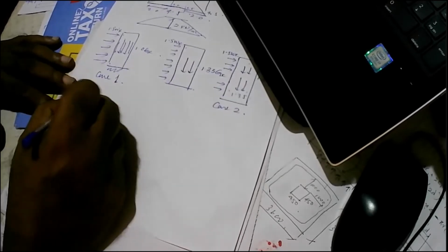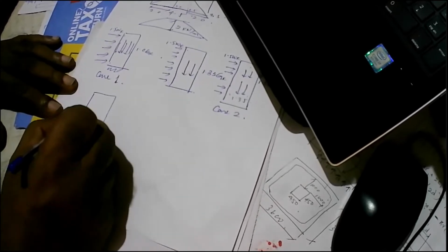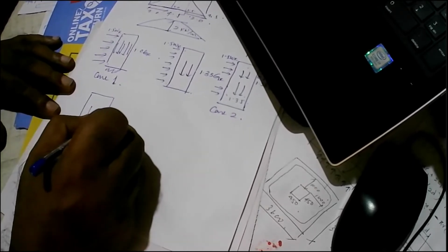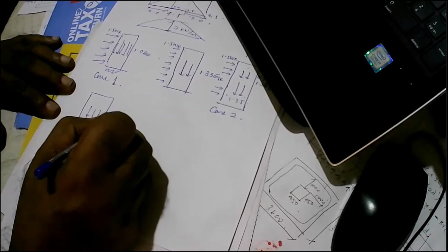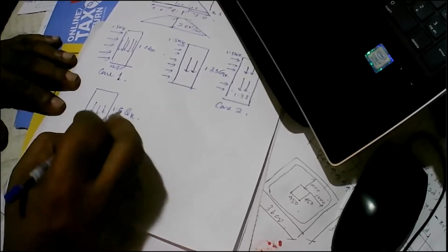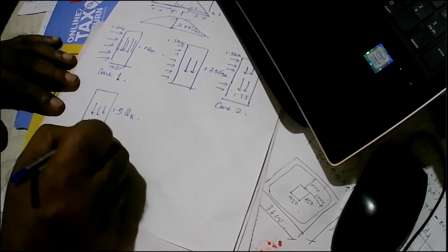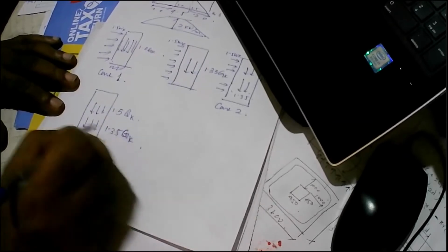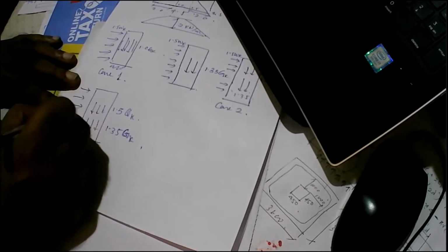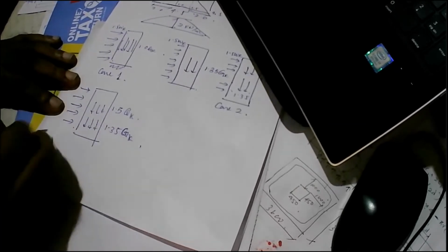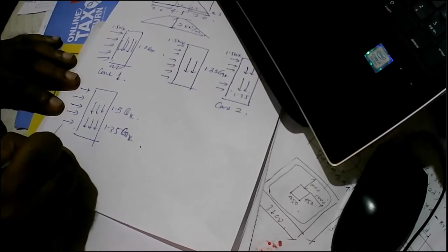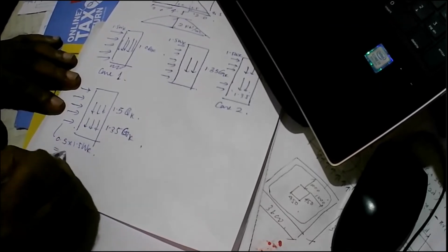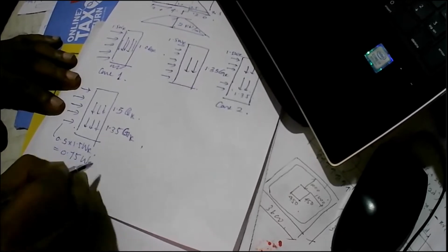And then we can get another case. That is the imposed load becomes dominant, 1.35 GK, but the wind load becomes the secondary variable load, and that is 0.5 times 1.5 times WK. So you'll end up with 0.75 WK.